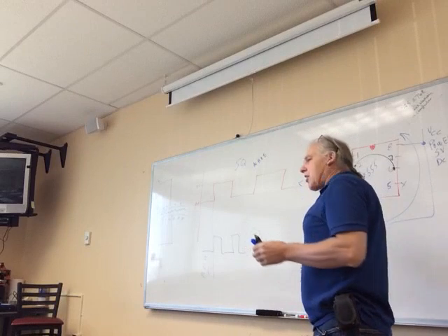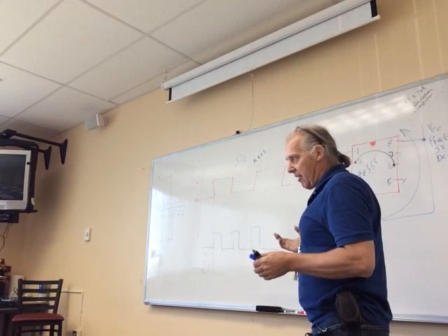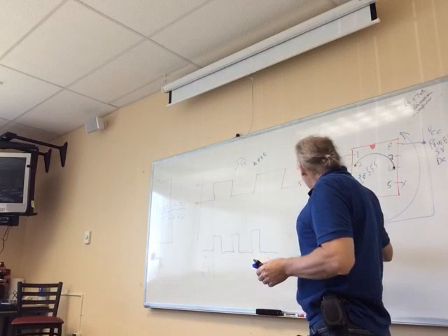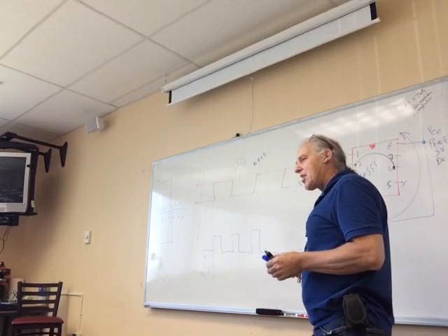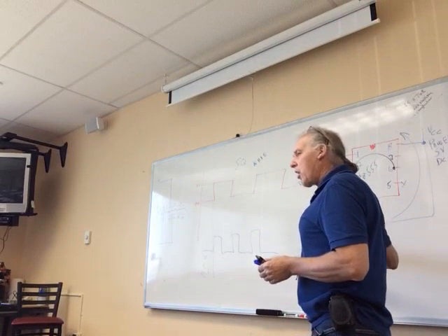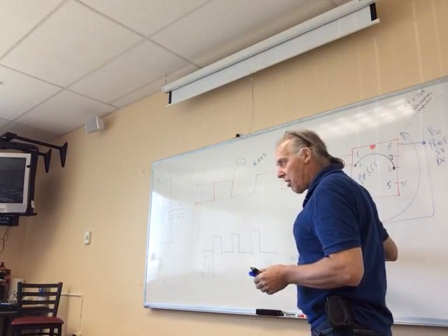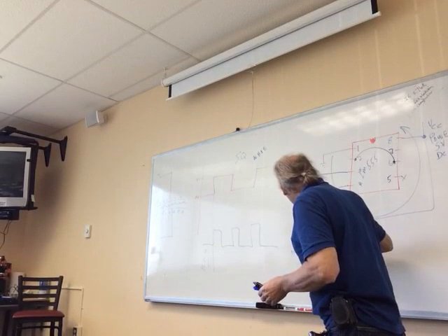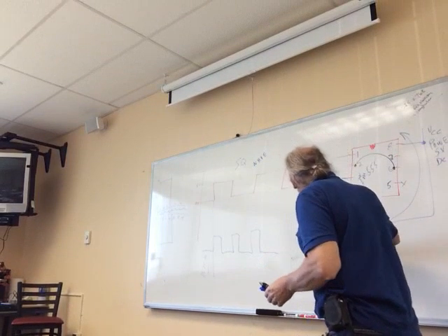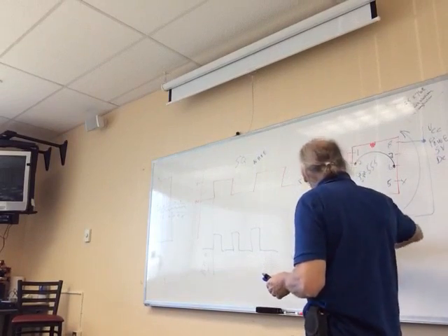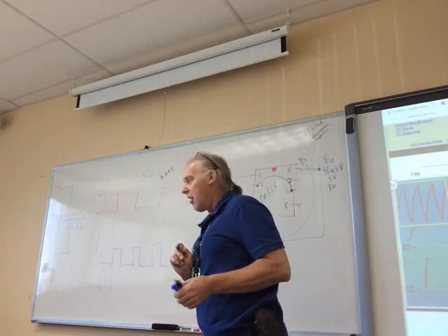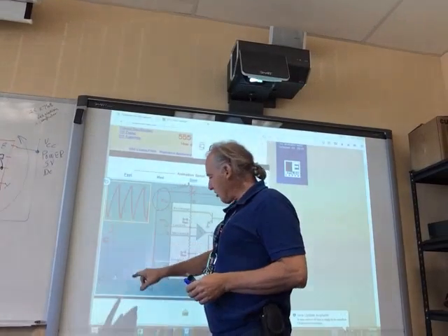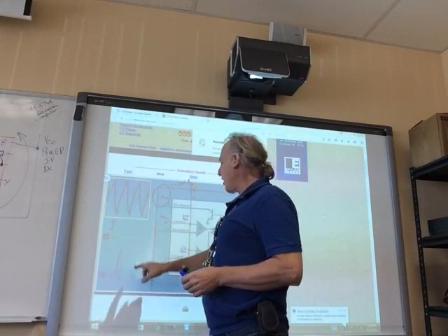So we don't really want to use like a 1 or 10 ohm resistor, because right away our power supply is pumping a lot of current through that resistor. But if we use something in the 10K range, a small amount of current will pass across that resistor. But the idea is that we can charge up the plates on this capacitor, and when we open the switch, they will discharge through the resistor. And we end up with this. Charge up, discharge. Charge up, discharge.